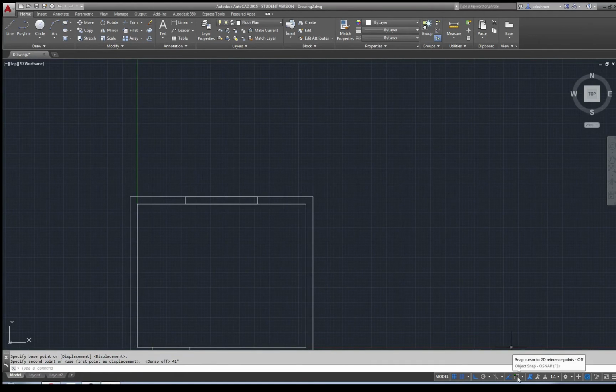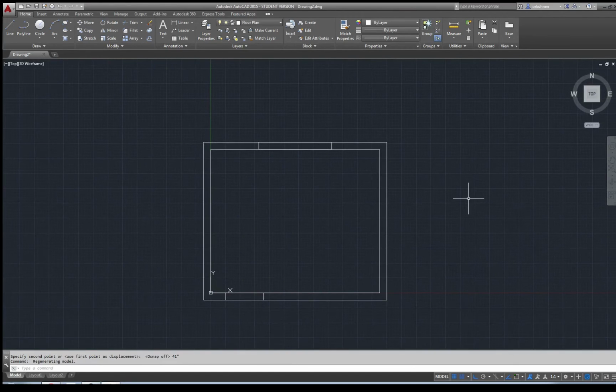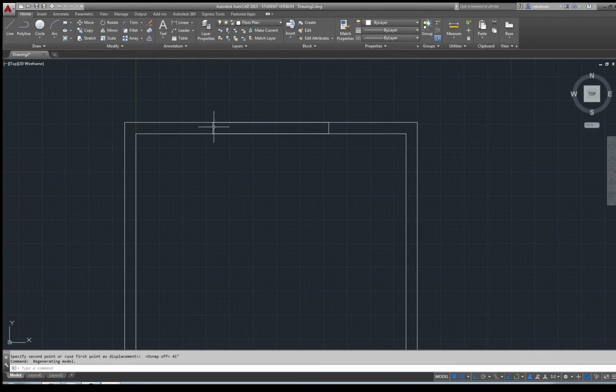So this is actually already a good point to mention that the snapping tools sometimes can really be tricky and impacting how your other tools are performing in AutoCAD. So easy fix sometimes. Turn them on when you need them, turn them off if you don't need them. I have another window here, also 62 inches, but 9 inches away from this corner. So this object is already made.